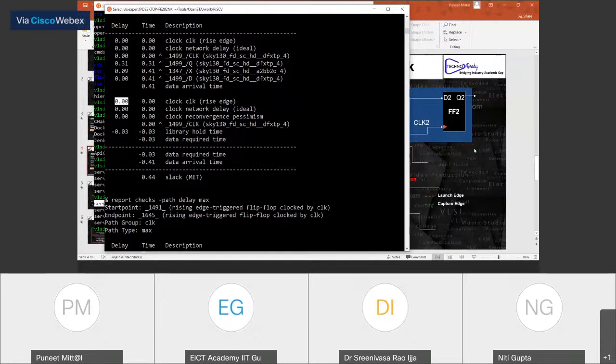This is a little bit of an advanced thing, but just for your reference, maybe you can go back and do a Google search or read some articles and figure out what a multi-cycle path is. In a multi-cycle path, right now our edges were after one cycle. In a multi-cycle, it is going to be after multiple cycles, maybe after 2 cycles, 3 cycles, after 4 cycles. So that is a multi-cycle path.